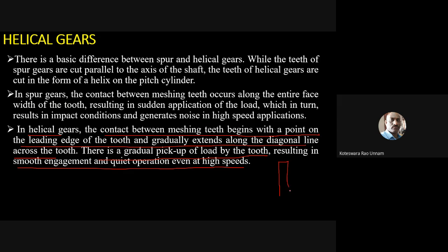So here, if you take two helical gears, this is another one, of course. Here the contact will be first at the leading edge. Because you have an angle, something like this, the two angles will be like this. So first the contact will be like this, and gradually it will move to the diagonal line across the tooth.